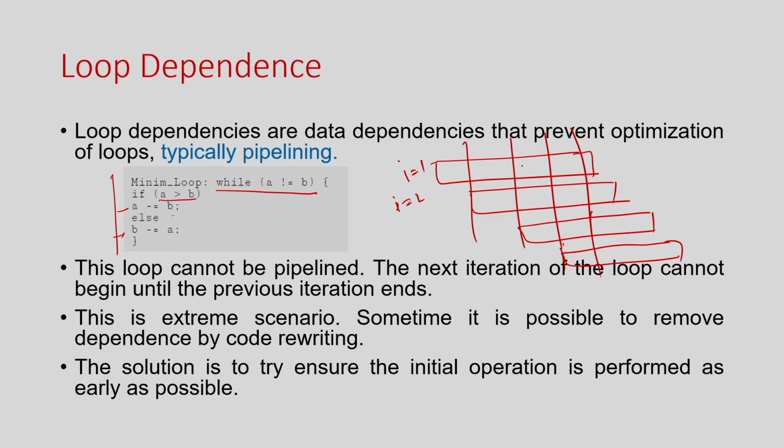Now, think about the case where iteration i plus 1 depends on the i-th iteration. Whatever data I need in iteration i plus 1 depends on the data of the i-th iteration. This is the well-known data hazard, as in normal processor-level pipelining as well. For example, say I am calculating q here and that is getting used here.